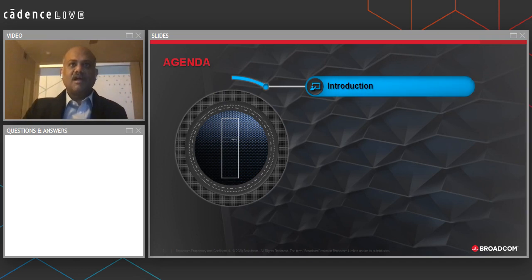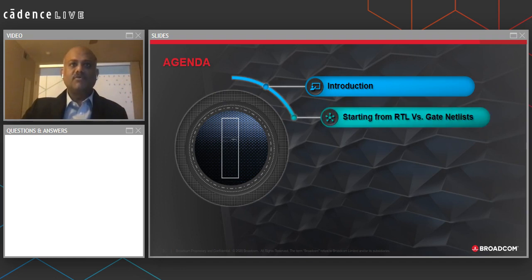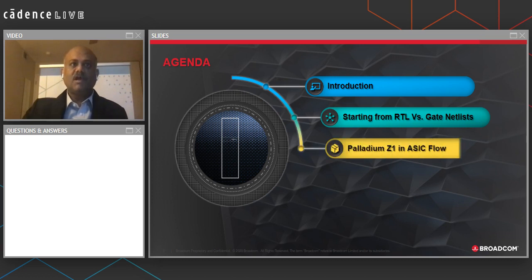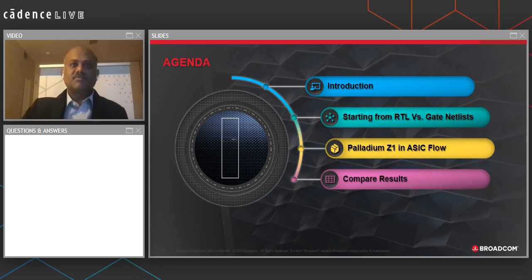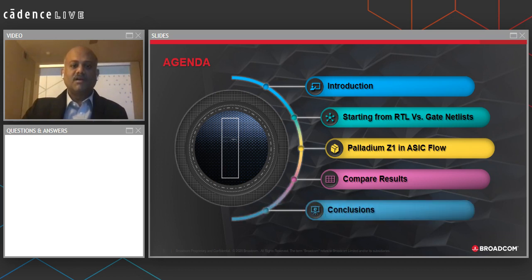In the presentation, I'm going to give a short introduction about starting Palladium Z1 flow from RTL and from gate netlist, about Palladium Z1 in ASIC flow, compare the results of RTL Palladium Z1 flow versus gate netlist Palladium Z1 flow, and conclude with what worked better for us so that you will have some takeaway from this presentation.